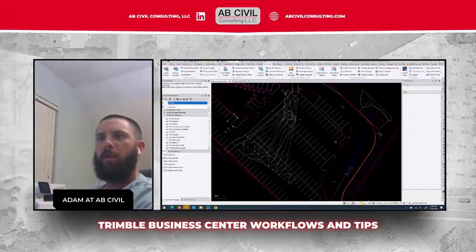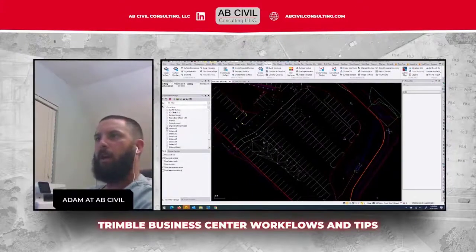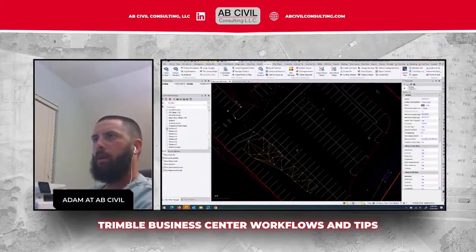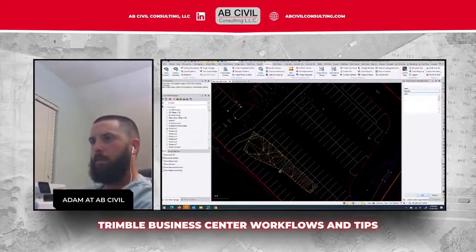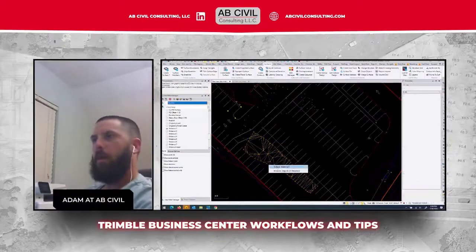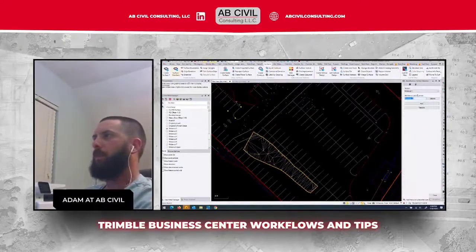It's pretty quick. So if you go back over to your surfaces, I'm going to turn off the surface I just made. And I'm going to turn on Undercut 1. I'm going to click on the surface, go up to Surfaces, and I'm going to do Edge Break Line, which is going to make a break line around that entire surface. And it's going to change the triangles a little bit. I'm just going to take that break line and I'm actually going to remove it from the surface because I'm just trying to use it as a boundary.